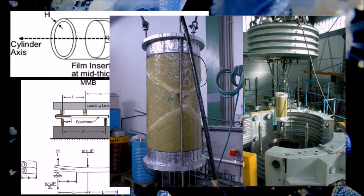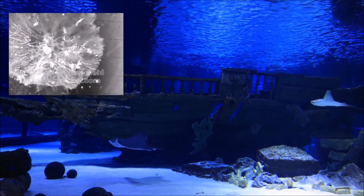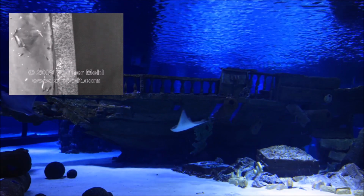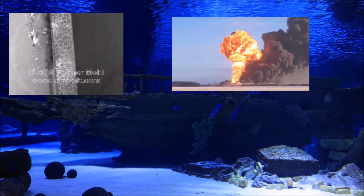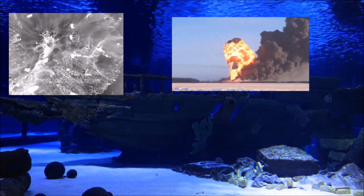Another type of defect is impact damage. Various researchers have studied the influence of impact damage on the implosion resistance of glass epoxy composite cylinders. Rather few data are available for carbon epoxy composites. As an example, damage in the form of dents is one of the most common causes of pipeline failure. They occur due to the impact of foreign objects and other causes during transportation, installation, and trenching.